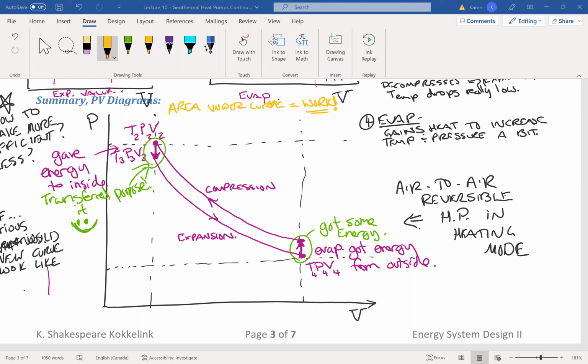All right, good, Jack. So yes, you're paying for the compressor. You're paying for that system. So the area under this whole compression curve is the work that goes into the system. Okay, this area under this whole curve is the work into the system.